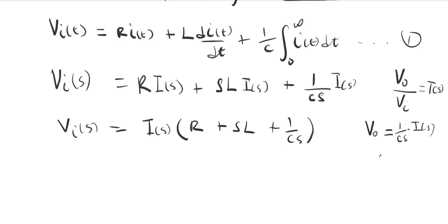Ohm's law says V equals what? IR. So in the frequency domain, if you represent the capacitor like this with a complex s, it will act exactly like a resistor. What you are doing here is just Ohm's law, nothing else, nothing more. The capacitor behaves like a resistor, and the inductor, once it is like this, will also behave like a resistor. Okay, that's by the way.